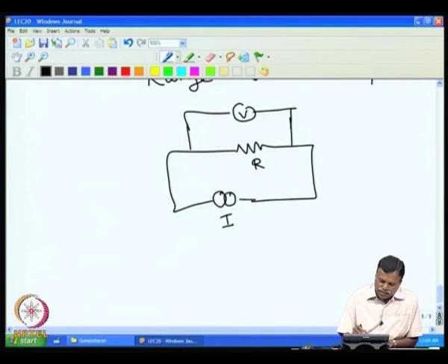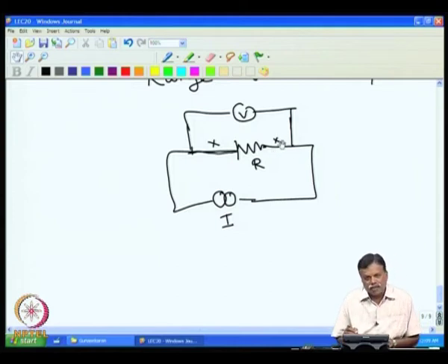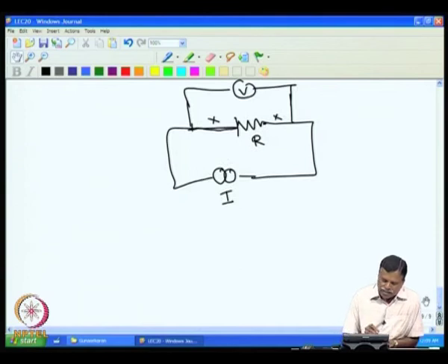because we will be connecting this resistance to this through a wire. So, you will have a contact resistance; even if you make it small and join this one, there will be a contact here. So, you will have an error due to this. Similarly, there is an error at this extra lead that has come in. That means you will be getting a voltage at this point that represents not only this resistance, but this plus this, and that is an error, and this error will be very high if the resistance value is very low. So, we call these contact resistance issues.